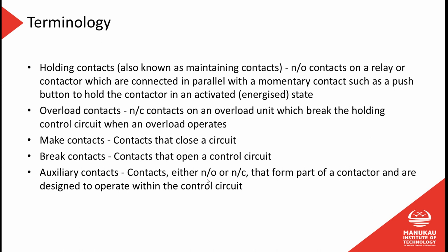If you recall in our practical rooms, not so much the emergency stop buttons, but the little push button switch on the side of the switchboard, that is activating a latching contact on a contactor. So we don't have to stand there and hold that button in. It's just a momentary press which activates a latching contact or holding contact to hold that contactor on.